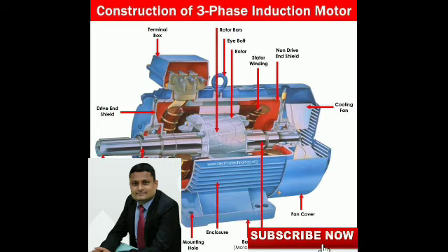These are all the checkpoints. So there is one assignment. Find the main dimensions of a 15 kilowatt, 3 phase, 400 volt, 50 Hz, 2810 rpm squirrel cage induction motor having an efficiency of 88% and a full load power factor of 0.9. Assume a specific magnetic loading of 0.5 Weber per meter square and a specific electric loading of 25,000 amp per meter. Take rotor peripheral speed as approximately 20 meter per second at synchronous speed.